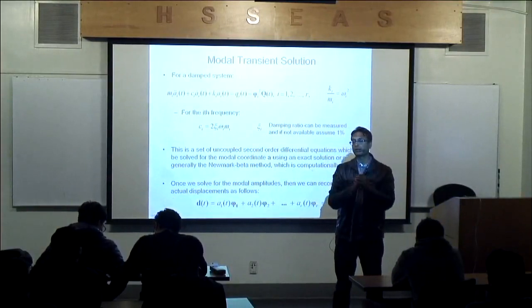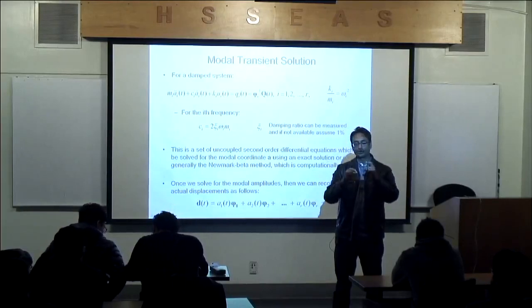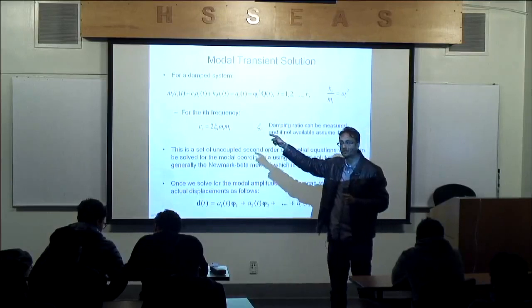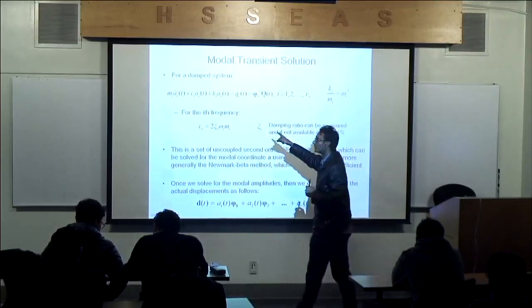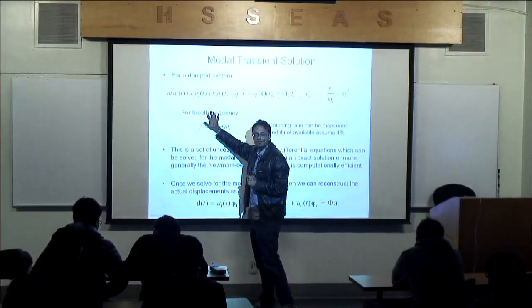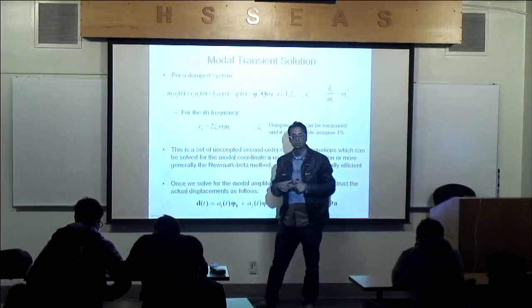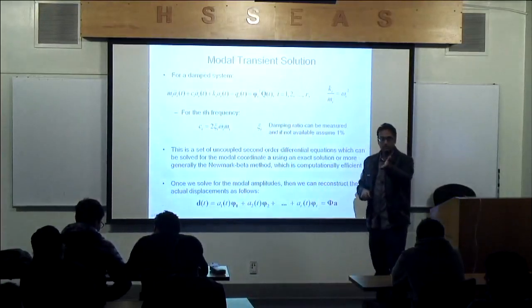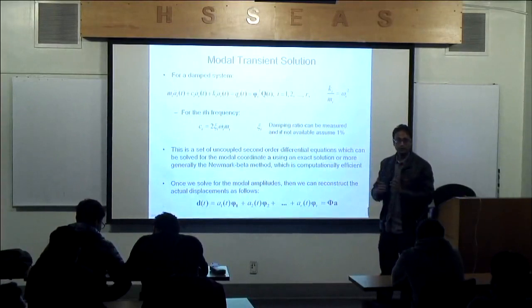Remember, maybe in mechanical vibrations, if you've seen it, you have a single mass with a spring, right? And you have to solve that differential equation? That's it. I reduce a very complicated system into 10 decoupled equations. 10 of them. Okay? It's fully decoupled now.